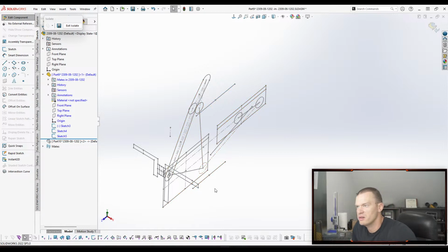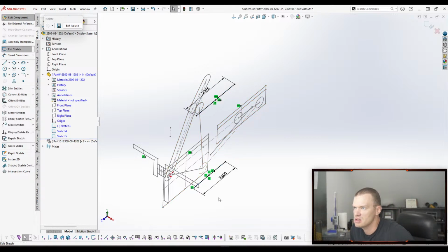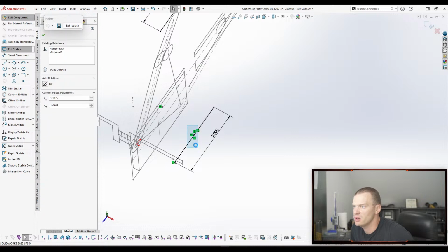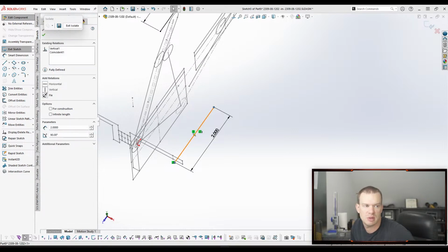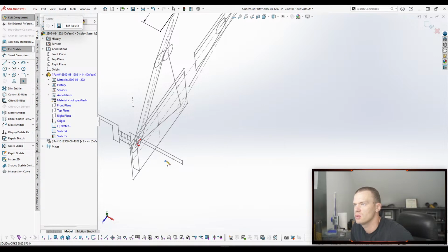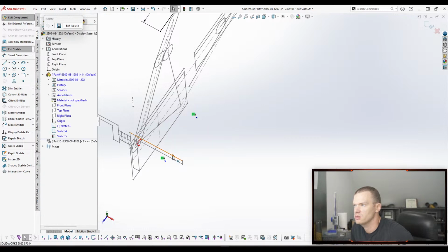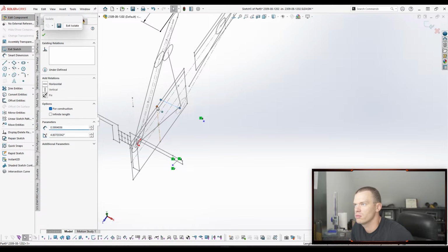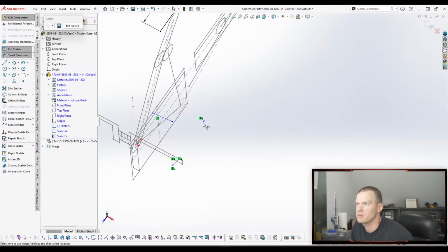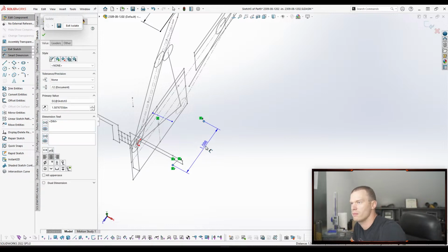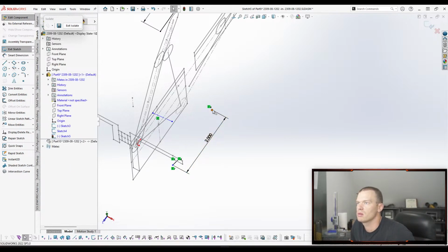And so maybe what we want to do is go in at the sketch, and instead of doing this point here and this length, maybe we do 2 points like this, set them vertical to this, and then do a symmetry line coming off of this here, and we make them 2 inches apart and symmetric about here.